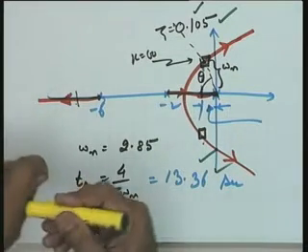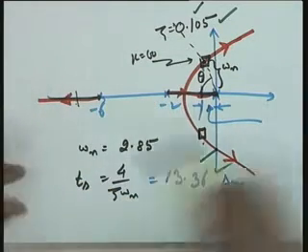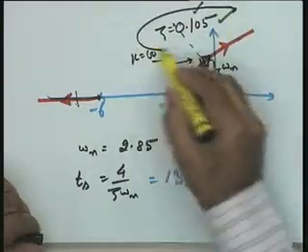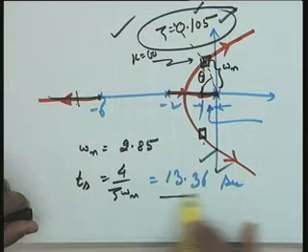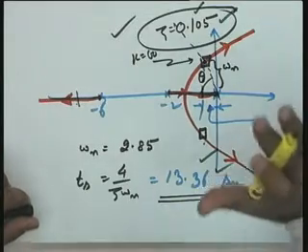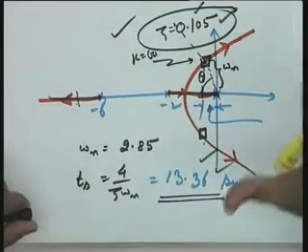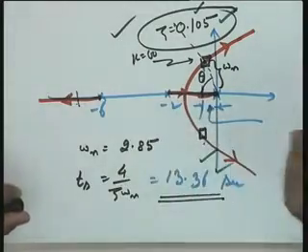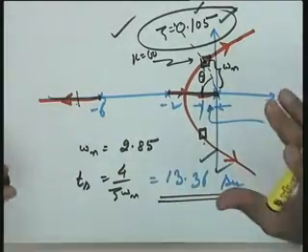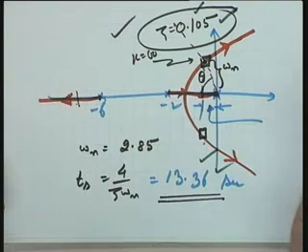Now, you see that for a general industrial application, the user is not going to agree to this design. This will be a highly oscillatory system with a lot of settling time. So, both the speed of response and the relative stability are poor in this case. It means only amplifier gain Ka could not meet your requirements on the steady state accuracy as well as the transient response.